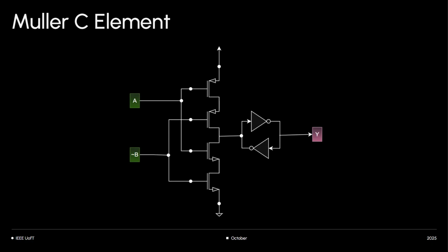That's a pull-up network, pull-down network. Can anyone tell me what MOSFET that is? A PMOS, yeah. Okay, guys, so that's the pull-up network. This is the pull-down network. This looks weird. For those who did 334, usually if the pull-up network is in series, your pull-down network is in parallel, right?